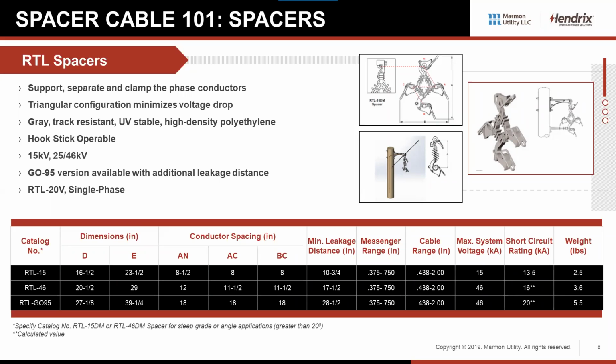The key thing about the spacers themselves is actually the material that they're made from. We mold these in-house from the same exact high-density polyethylene that we put on the covering of the conductor. So we know that from an electrical perspective, they're completely compatible. That becomes an important piece, especially historically, as other manufacturers have come in and made spacers from different materials that have different electrical characteristics. Our experience has always been we want to use the same exact polyethylene that's on the covering of the conductor.